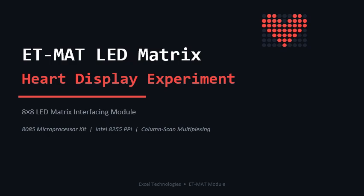Hello everyone. Today I will be presenting the LED matrix experiment, and in this experiment I have an innovation in which rather than displaying a character, I will be displaying the shape of a heart. This experiment demonstrates how we interface an 8x8 LED matrix with an 8085 microprocessor kit using the 8255 programmable peripheral interface. We use a technique called column scan multiplexing to display a heart pattern efficiently on the LED matrix using software control.